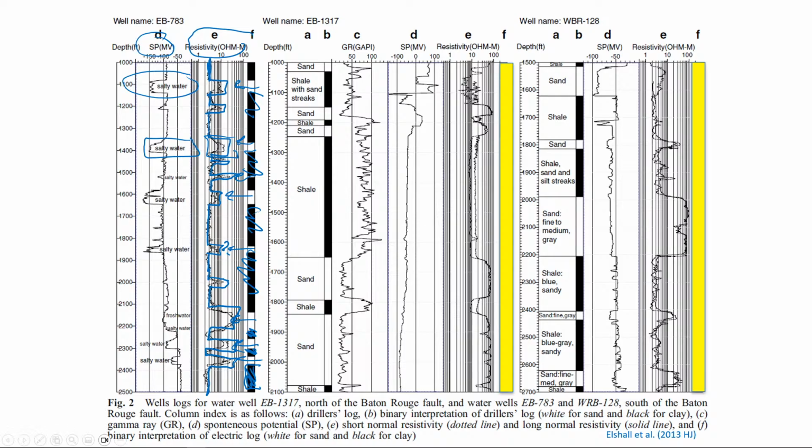So now you see, you got a lot of information, and that's how we will be able to characterize the subsurface. We will be able to find where the pervious and impervious layers are. And remember, we talked about this when we talked about heterogeneity, hydraulic conductivity heterogeneity, and I told you you need to define what level of heterogeneity we are interested in. So if we are interested in modeling salt water intrusion in a city like Baton Rouge, what is important is not to understand the variation of the hydraulic conductivity of different sand. What is more important is to find, okay, this is sand where water can flow, and this is clay, or impervious, where water does not flow.